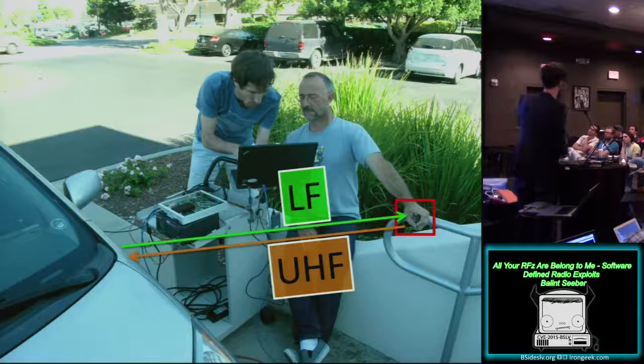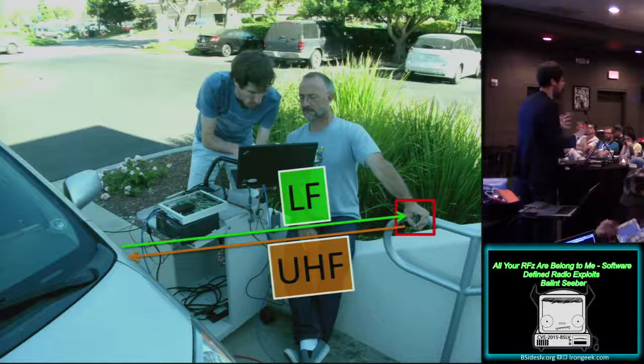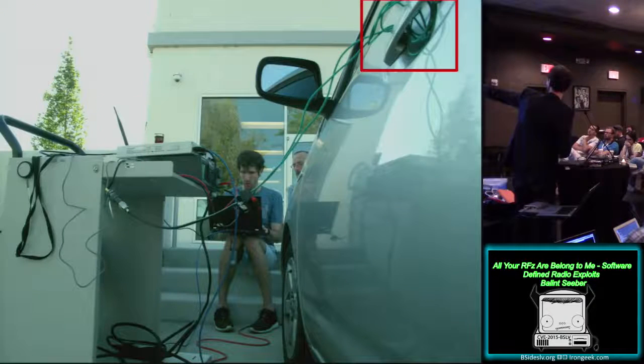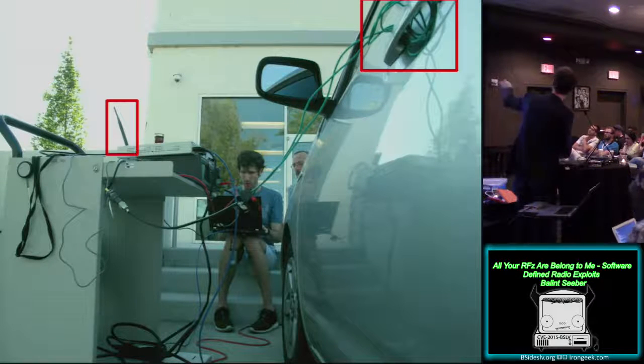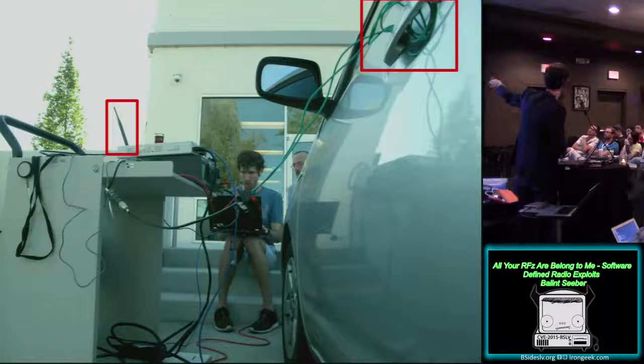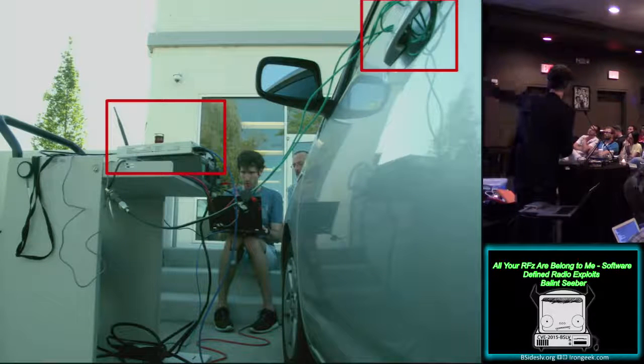So the response is sent back over UHF, as it would be if you press the button on the remote control. But in this case, I just wanted to look at both sides of the link to see how that transaction actually took place. So there I've got an X300, which is listening on the LF from the car. You can see I've just got this really, really high-tech LF loop antenna that's shoved into the door handle, and then the UHF is being picked up on this whip antenna there.